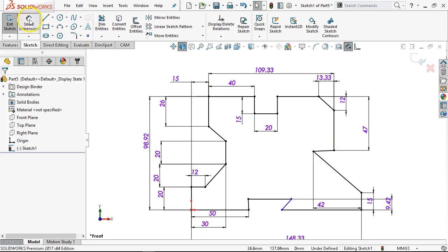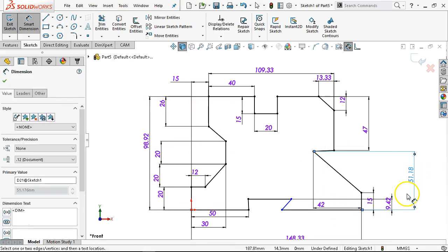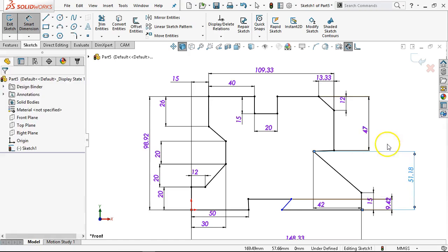So if I try to go back to put in the 30, for instance, this is where we're going to start to see, I turned mine to don't show for make driven, or what's the other one? Allowed to drive or make driven. This automatically went to a driven dimension on mine. Okay, so when that little box pops up and says, do you want to make this dimension driven? I click don't show. I'm looking for that little bit of a flicker, and that these lines being in the lighter gray, I know that that's driven.